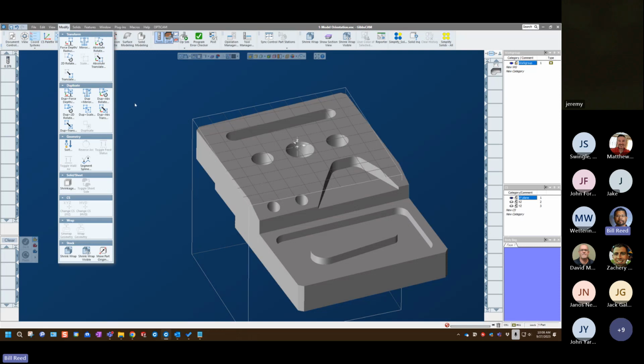The difference between standard rotate and standard translate is that standard translate is kind of an incremental translate. I want to move it a distance from wherever it is, or an angle from wherever it is. When you put absolute in front of that, it's telling it I want to move it from an angle to an angle, or from a position to a position. So there's a subtle difference there, but it is pretty powerful.